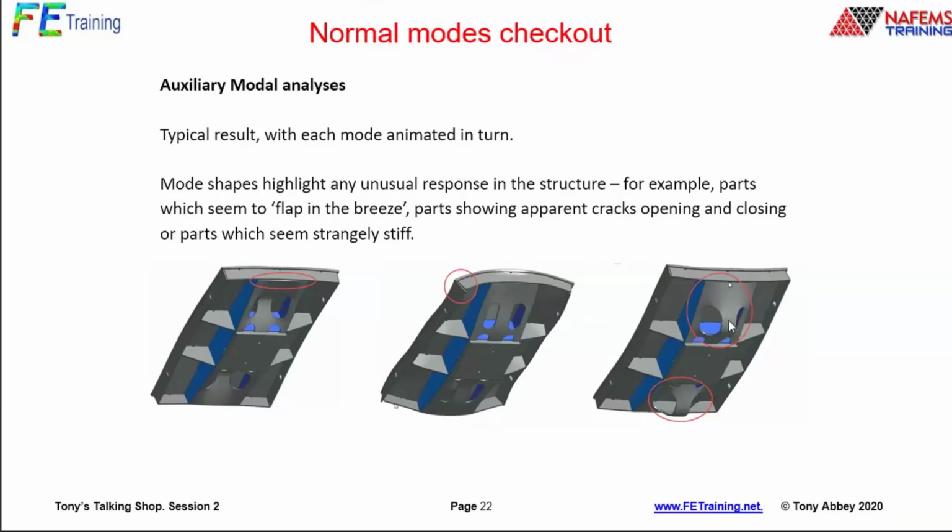So they actually, on the fly, as we're going through the course, they kind of said, well, let's take that material which is there and apply it as a bottom flange to the longitudinals in here. And then we're stiffening the structure up. We're doing something useful with that structure. So when I'm teaching designers, I really emphasize this as well. It gives you an insight into relative stiffness of the structure, and you may well find something like that.